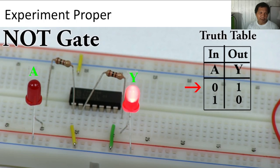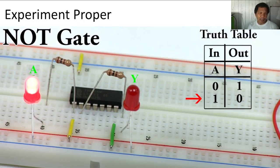Okay, now let's try this one. We will connect and then we will power on the gate. Initially, this is connected to the ground. That is why the input LED is turned off. Once the input is turned off, since this is a NOT gate, the output will be logic 1. It will turn on the LED in the output if the input is in logic 0. The same is true if the input is logic 1, as indicated by the LED, the output becomes logic 0. That's how the NOT gate works.